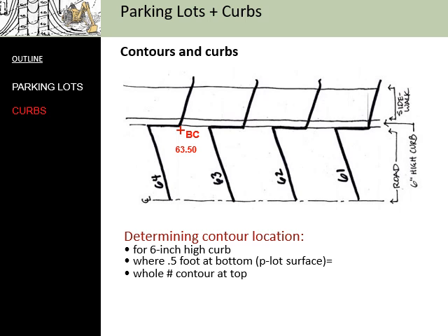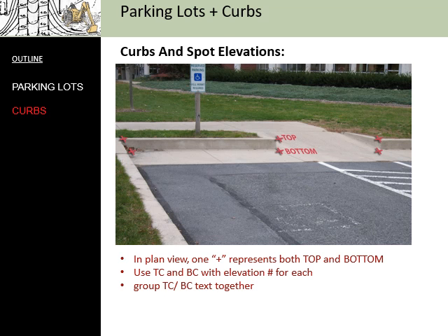So this is a skill you're going to use as you are designing your parking lots and getting your contours correctly drawn on them. Now, to have a parking lot properly built, we need a lot of information about these curbs. What we need to know is what is the elevation at the top of the curb and at the bottom of the curb, and we need to know this about specific locations within the parking lot.